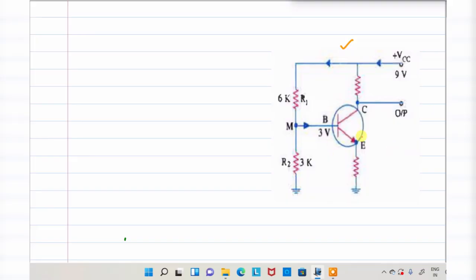Next, we are moving to another example. You want to make a transistor be in the on position. The base voltage you require is 3 volt. With the help of the voltage divider rule, we can calculate whether the 3 volt is satisfied or not. What is the supplied voltage here? 9 volt. That means the voltage across this particular point is 9 volt. So this is a series combination, right? Whenever this is a series combination, 6K and 3K are connected in a voltage division arrangement. So I want the voltage across this particular 3 kilo ohm resistor, then only you can calculate the base to emitter voltage.